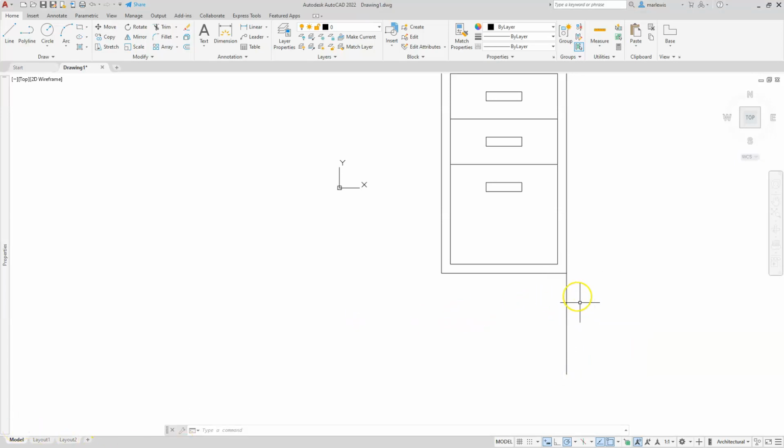All right, so the next thing I'm going to do is I'm just going to rotate this slightly. So I'm going to select it, select this grip, spacebar twice. I'm looking for the word rotate here on my command line. Next, I'm going to type in which direction I want it to go. Remember that the angles are going counterclockwise, so I'm going to type in my 15 degrees, and it should bend it out that direction.